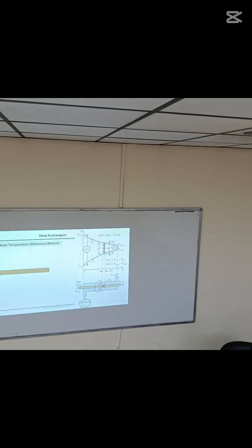All right, if it is not linear, then we need to find out this log mean temperature. Why is it log? Because when you write its equation, a log term appears. So we will end up with the same equation which we derived in internal forced convection, the log mean temperature difference. But here the derivation is different because there you had only one fluid, and the condition, if you remember, was constant surface temperature, and the other fluid's temperature was changing like this.